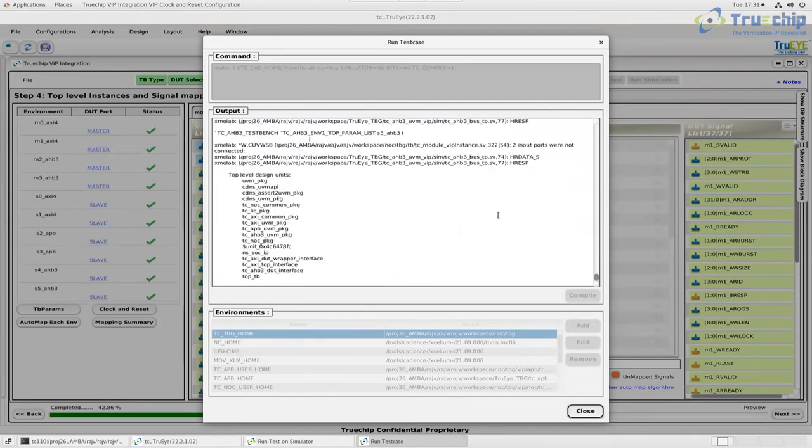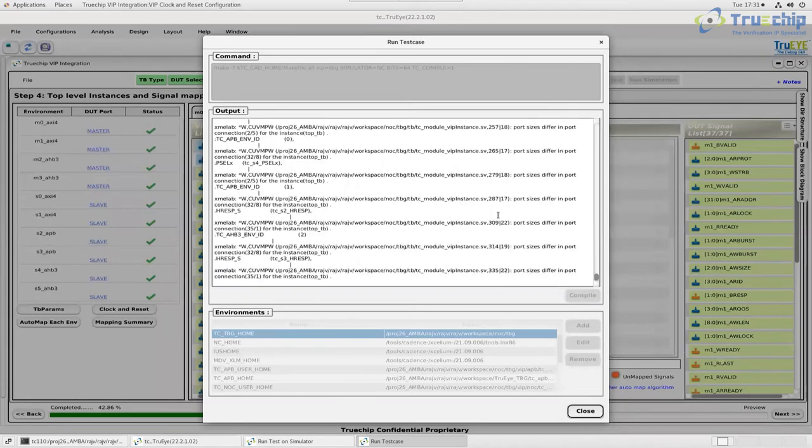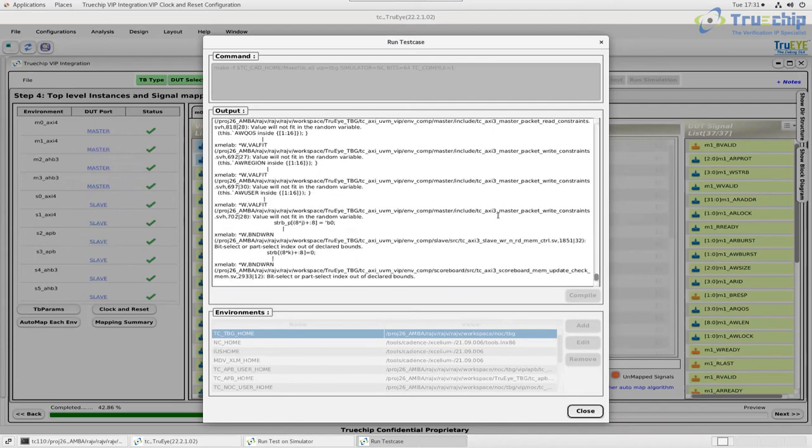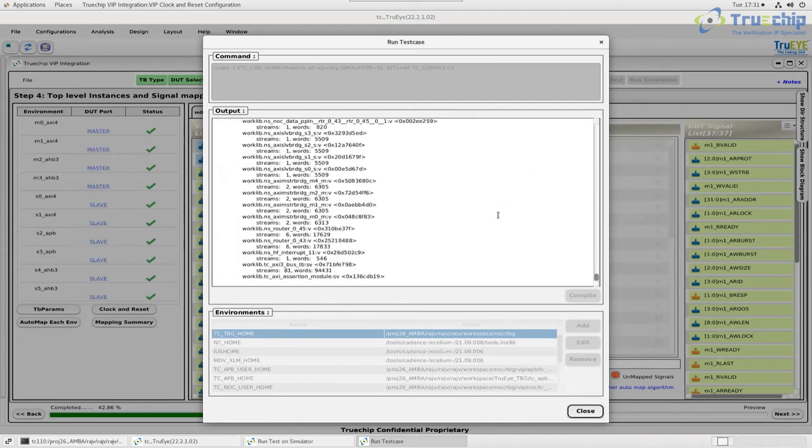Otherwise, in the conventional method you need to take a DUT instantiation, take a VIP interface instance or a VIP wrapper instance, take some wires, connect both of them, and assign some values, using an interface or manual assign statements. So the user effort has been reduced here.